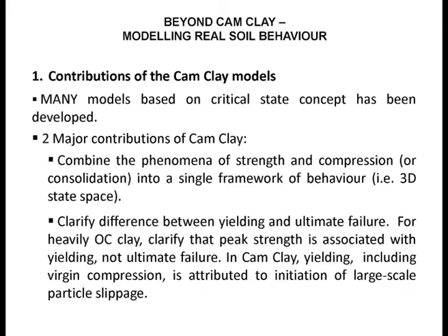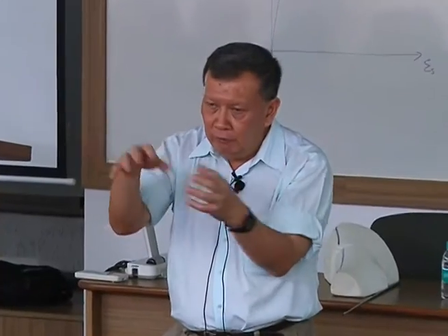the initiation of large-scale particle slippage. That means you got particles starting to slide past. Rearrangement, okay, rearrangement. And in a sense, you can see why it is plastic. Suppose you got a bunch of particles and you press it and the particles rearrange and repack themselves. If you let go, if you unload it, if you allow the load to go, will the particles automatically unrearrange themselves? It can't. Particles will not unrearrange.